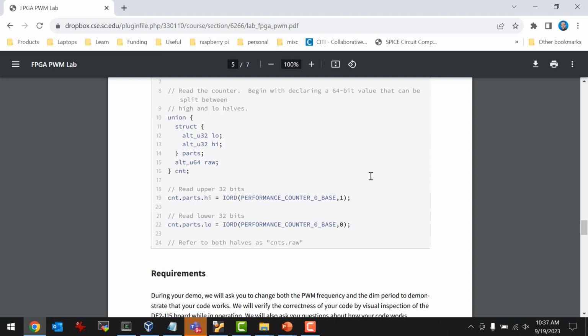I think it was when we upgraded Quartus to 18. We used to use Quartus 16. We went to Quartus 18, and they changed the compiler. And GCC suddenly became incapable of doing that. Like there's a bug of some kind in GCC. It would not allow us to do it that way. So then we discovered that the only way to do it was use a union in C, right? Which probably makes more sense, but the code is a lot more complicated than just reading it twice, shift and OR, right? So you can use a union.